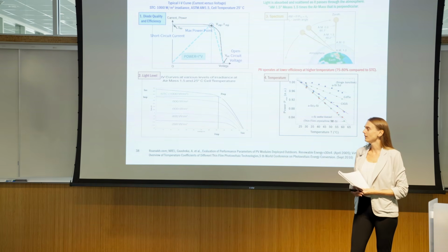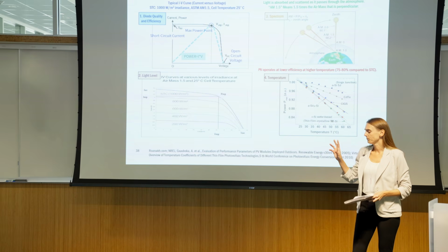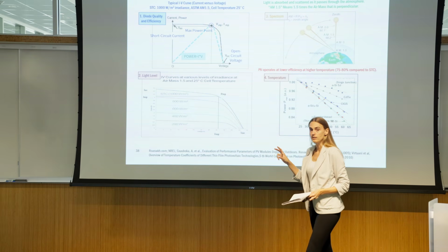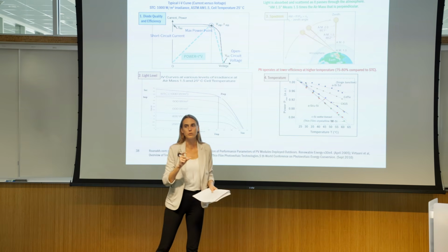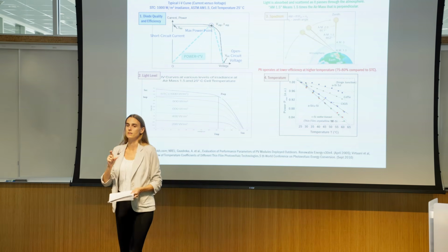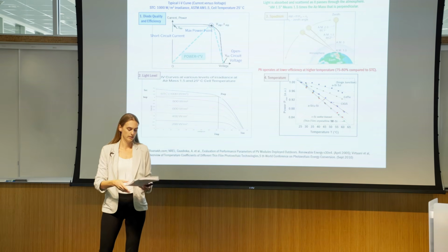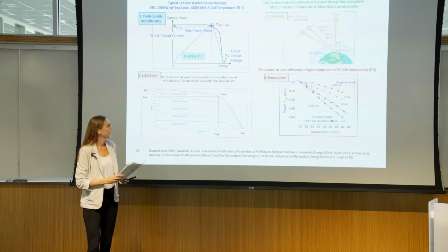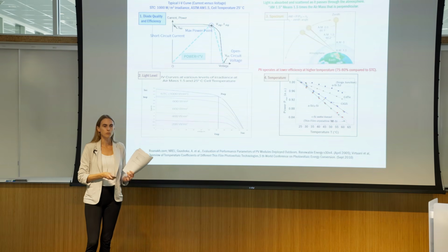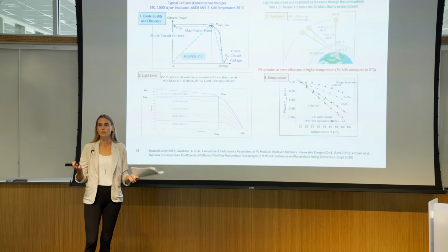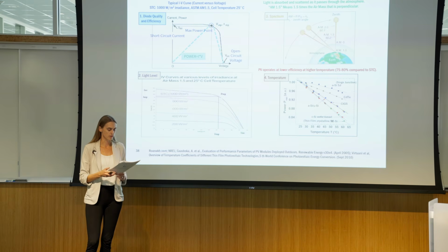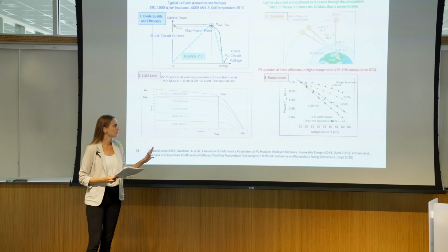So if you see solar capacity given in AC, that means that it's typically 20 to 25% lower capacity than its DC rating. It also means that the AC rating is typically under what are called performance test conditions, which are much more reflective of the conditions under which solar projects are operating. So it's something really to keep in mind.